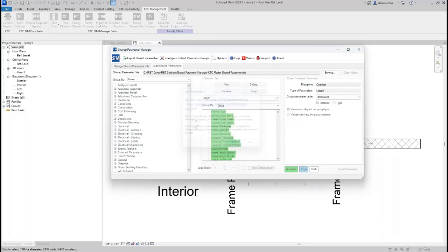And it's going to take the definition of every single parameter that you've chosen in that set, load them into your family, set the properties and the groupings as were defined here, and you're done. Now you can turn around and build the rest of the family, start drawing the reference plans, associating the dimensions, creating the geometry, flexing and testing, boom, away we go.